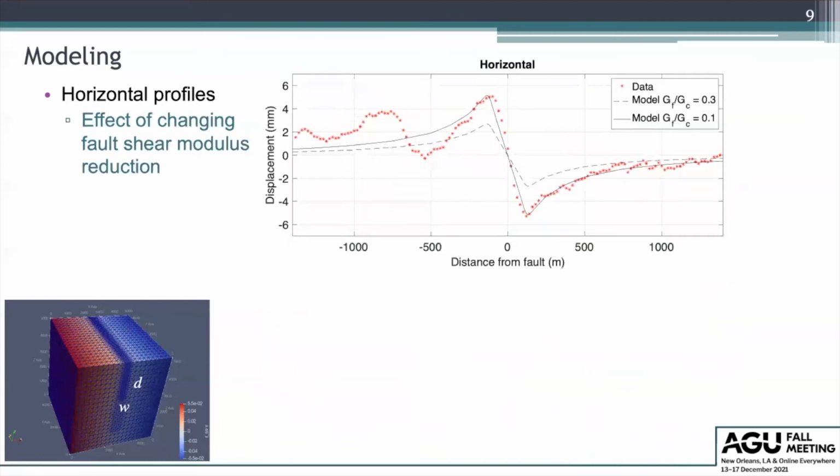And when you don't scale, the amplitude drops with the smaller depths in a similar trend as the horizontal. So next, in order to match deformation amplitude and shape, we further played with the shear modulus ratio, finding an even smaller one that will stretch up the curves. What's given here is for a depth of 250 meters. If you use 500 meters, the ratio will be larger, but the overall fitting is not as good.